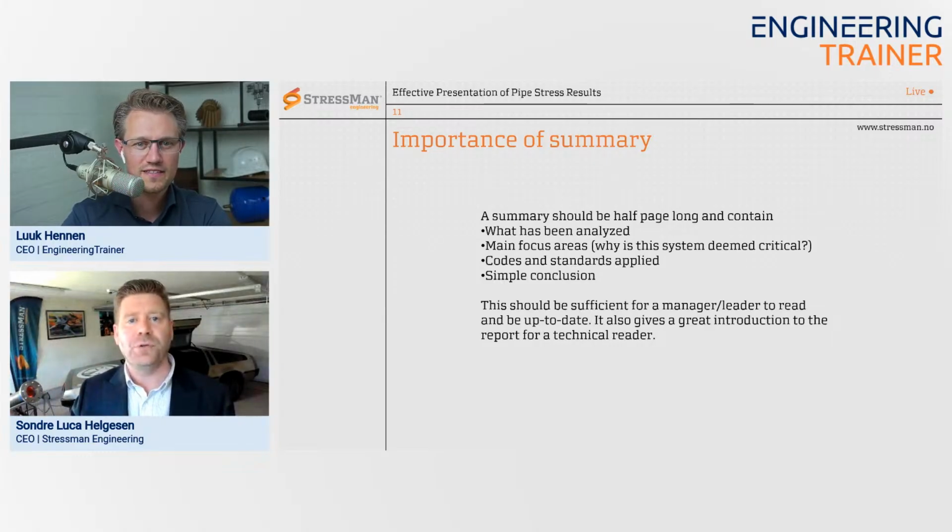Maybe looking into the stiffness of the supports. Maybe that gives you a bit more flexibility, and that reduces your thermal loading on the pump. So basically, you have to get within the allowable. If you don't get within, of course, you have to tell. It depends on how your project is set up. Maybe your company is also doing the design, and you're delivering directly to the end user. You could ask for a technical deviation on it.